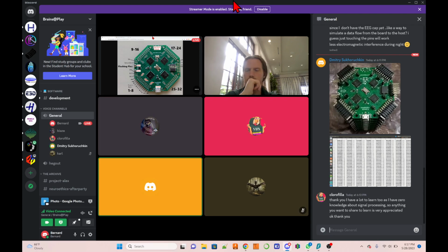So it's better to use gel electrodes with all gold connectors. All connectors need to be gold, because non-gold will add impedance. Use fewer connectors and more soldering: solder everything, or use gold connectors.